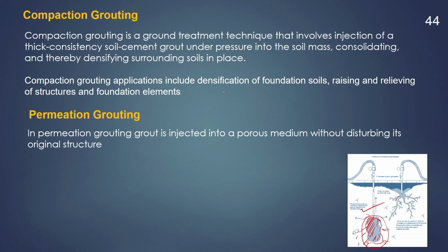This is generally carried out for densification of the foundation soil and for raising and relieving structures and foundation elements. Here we need to remember that in compaction grouting, a very thick consistency grouting material will be injected into the soil with a large amount of pressure, and once injected, it will get solidified and thereby compact or compress the soil surrounding that area, and therefore increase the strength of the soil.